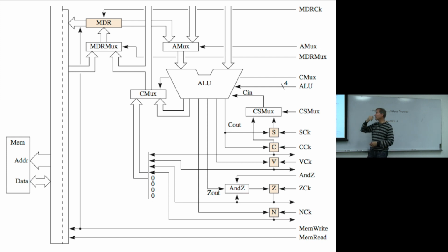Well, yes, but that computation of the carry and the penultimate one, that's all done inside the ALU. But outside the ALU, how can V get set? It's one of the output lines from the ALU. There's a V output from the ALU, if you go back and look at that. All right, and it can be clocked in with the VCK. And then it can also go to that rightmost nibble, one of the bits of the rightmost nibble.